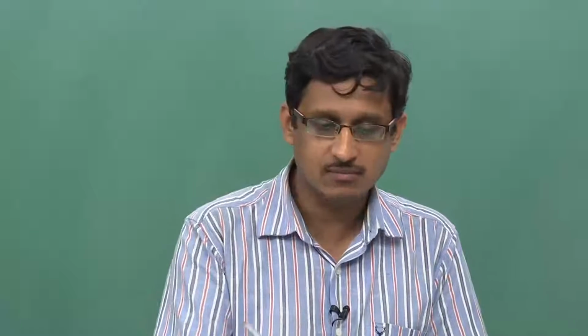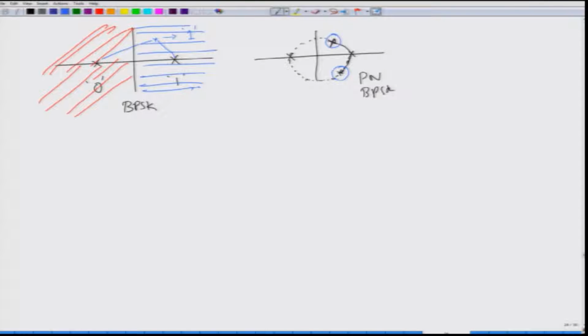If you add some ASE noise around that, then this would be the situation that you have. So, you have some ASE noise coming from the amplifiers, coming from the interaction of amplifiers with everything else that we will look at. Your received signals can be anywhere here, and of course, they can be rotated by this particular value. So, you see that with this received constellation you are still not making much of an error. And primarily the reason for this is that the phase noise is still manageable, because it is only covering one segment over here.